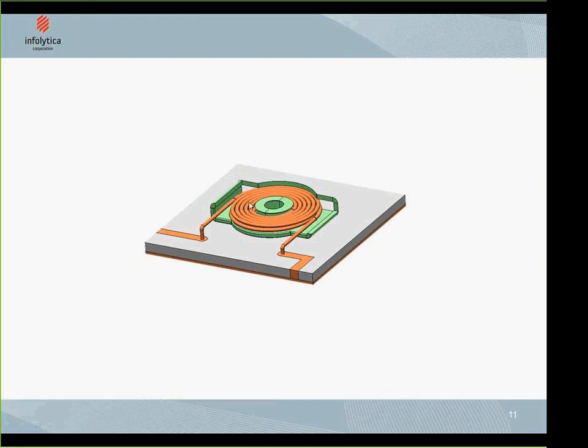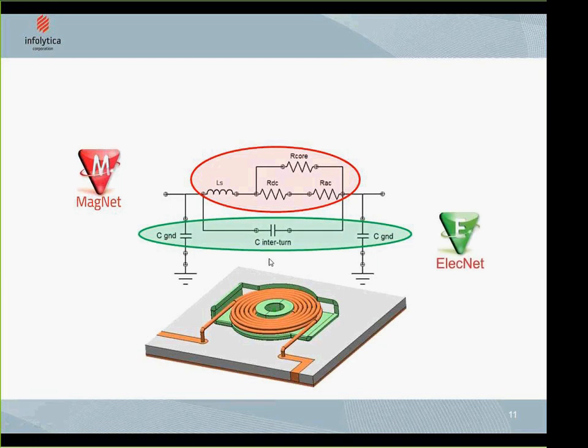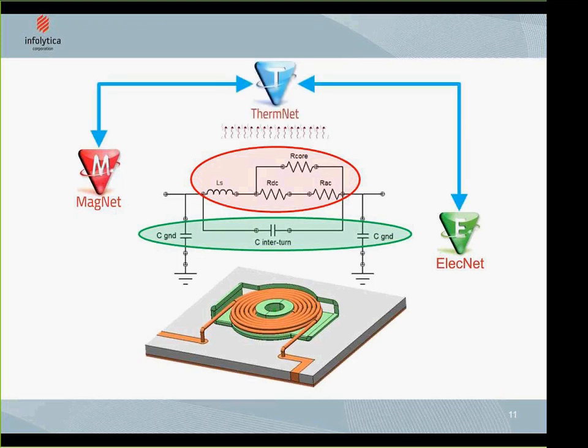One may want to estimate the parameters of this inductor. In this case, it depends on the operating frequency or the operating range of your device. If I'm interested in inductive and resistive components, then I can use MagNet to estimate the parameters of this device. If I'm interested in capacitive components, then I can use ElecNet to do the same. And if I want to see how temperature affects the device performance, then I can couple the solves to a thermal solver.